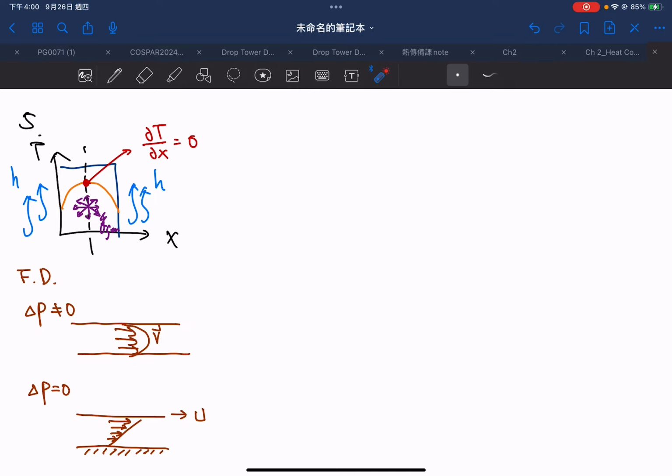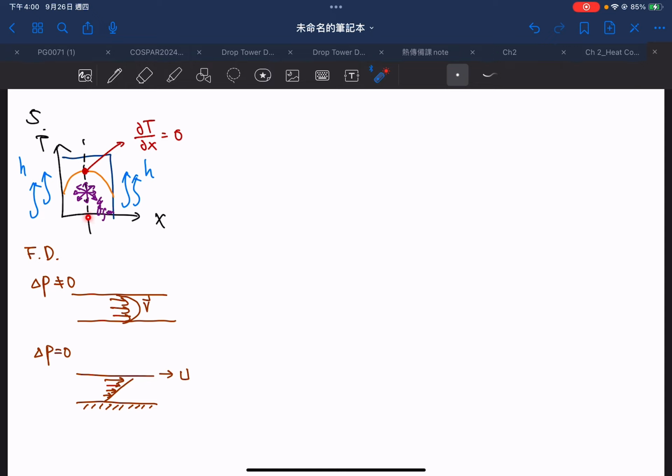Okay, so this is quite similar to heat transfer. If you have heat generation, the temperature distribution will not be linear. It will be either parabolic or a slightly more complicated polynomial. So just remember, if you see that the velocity profile is of parabolic form, then there might be heat generation inside of the object.